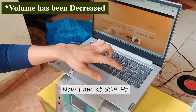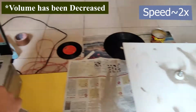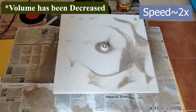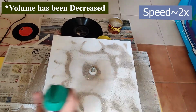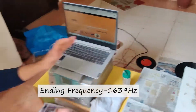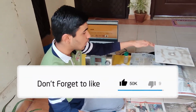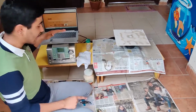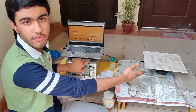I'm at 591 Hz. And here I have reached the limit of this system. This system cannot go any further because there is no amplitude left for the speaker to vibrate in. Also, there is a limitation of the speaker as well as the audio amplifier. This cannot output as much power as it needs on such high frequencies.